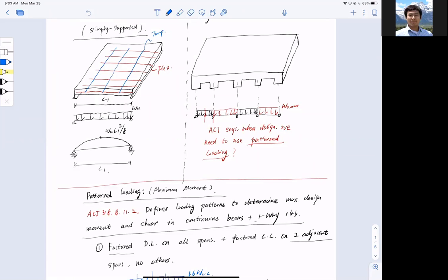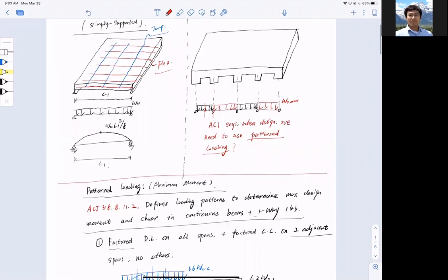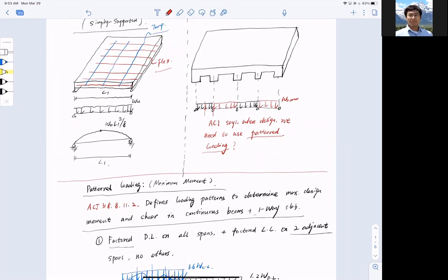Indicated as blue and red, you provide different reinforcement. If you forgot how we determine that, please see the previous lectures. That covers the calculation details about one-way slab reinforcement configuration. Now we went on to talk about the continuous one-way slab. The difference from the reinforcement we talked about is the support condition. Previously, we calculated moments using the simply supported condition. But for continuous one-way slab, the supports are spaced apart in a continuous fashion, so we cannot use that equation for moment calculation. They use different equations.